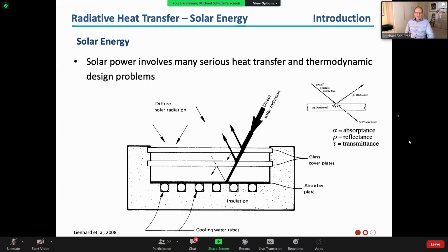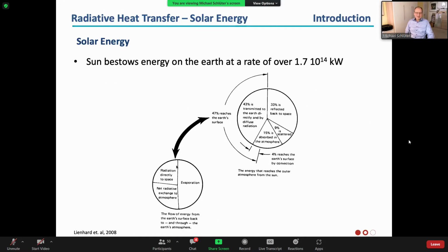Okay, another point that was mentioned was to increase the surface area. Yeah, surface area, of course, is an important point, but you don't increase the surface area with this plate, because what we're interested in is to increase the surface area here for the heat transfer, right? And not here, because this is just a plate that needs to be passed by the radiation. We just need to use this plate for better isolation against heat loss.